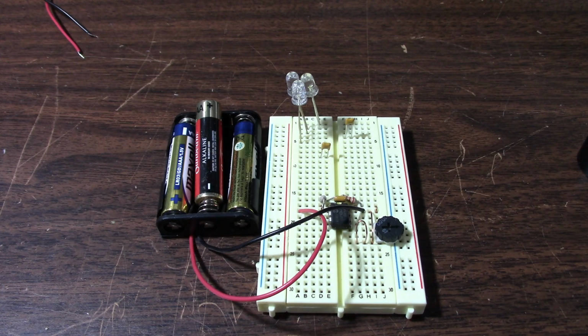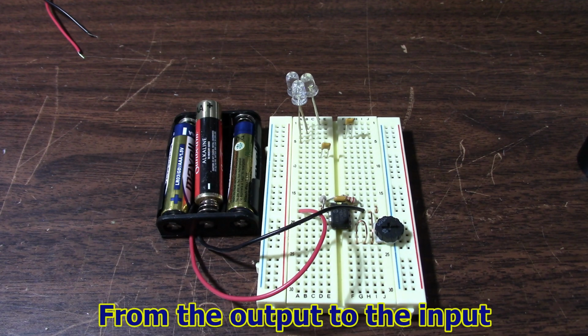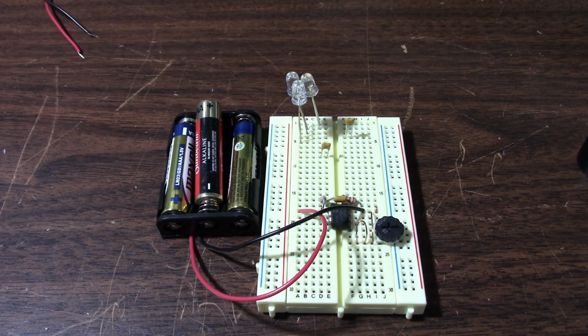Now there's a lot of ways of creating square waves. One way you can use those digital logic chips like the 7400 series or stuff like that. One way is using a hex inverter, and you feed that signal back using a resistor and capacitor to set a time constant, and you can generate square waves that way. And I played around with it and really wasn't happy with what I was getting. I think I could do better.